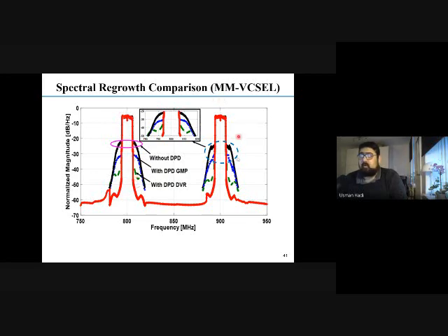So there are two channels, so you have two references, one at the 900 carrier and then 800 megahertz. And then with the performance of the GMP and DVR linearization, you see that GMP is blue, DVR is green, and DVR is actually outperforming the GMP one. So it is very clear that DVR is performing better as compared to GMP at 800 and 900 megahertz.